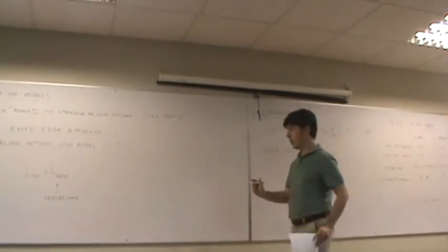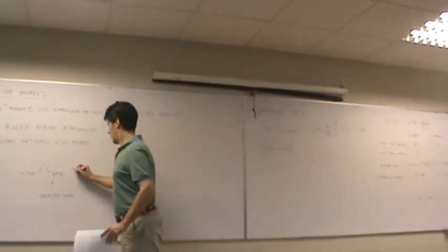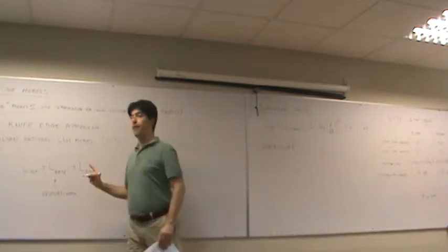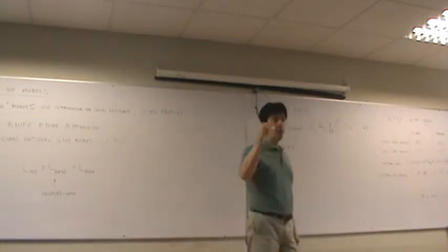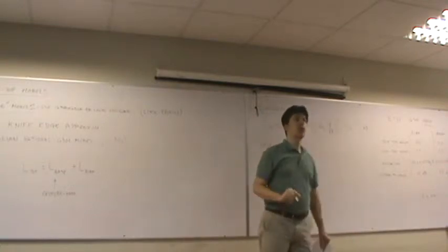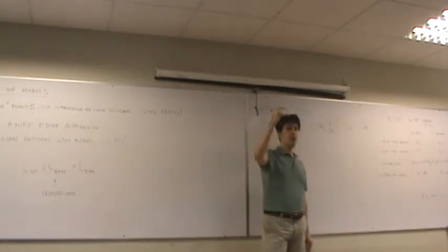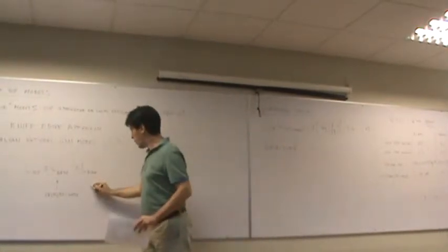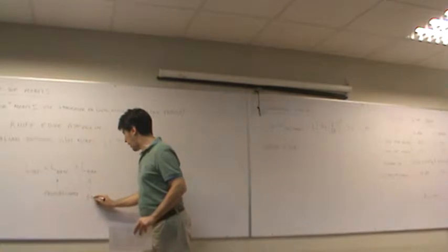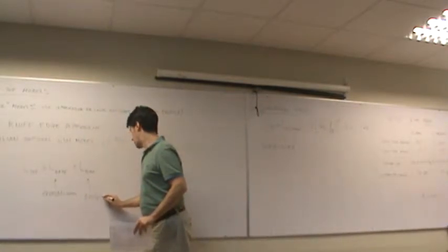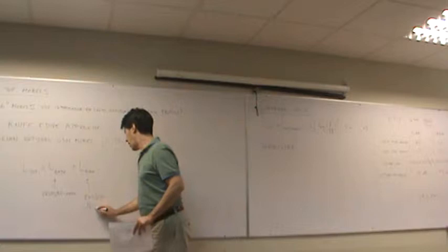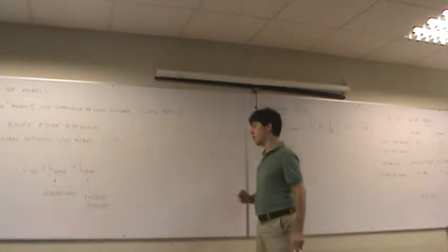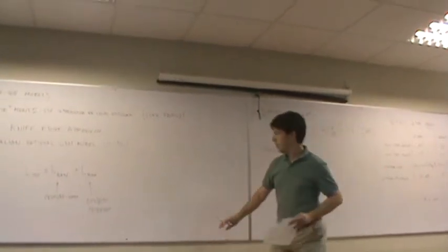On top of those losses, you have the losses due to knife edge diffraction, because you are propagating over the rooftop. And those things are calculated with, you already know it, the Epstein-Peterson method. Don't worry, we will do exercises on this method. I know you are happy, you are looking forward to that.